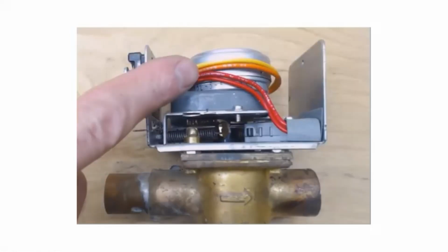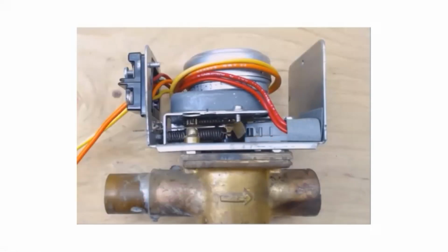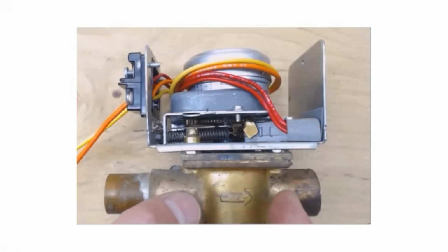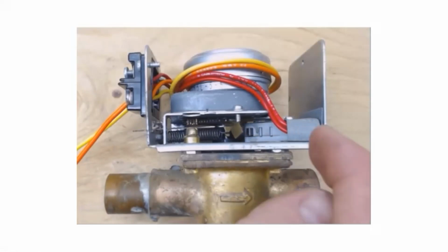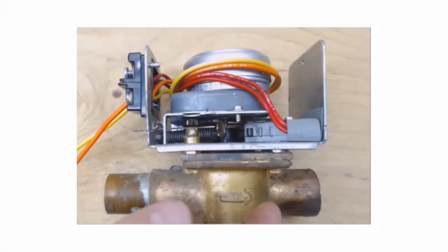So you see our motor's turning, which makes our gear turn, and the tab is going to press up against the micro switch, and you're going to hear a clicking noise. That means that the two red wires are now touching, and that's an indication that the valve is actually open. Now let's go ahead and disconnect our power. Now you heard that click, which means that the two red wires are not touching, and now our valve is closed.